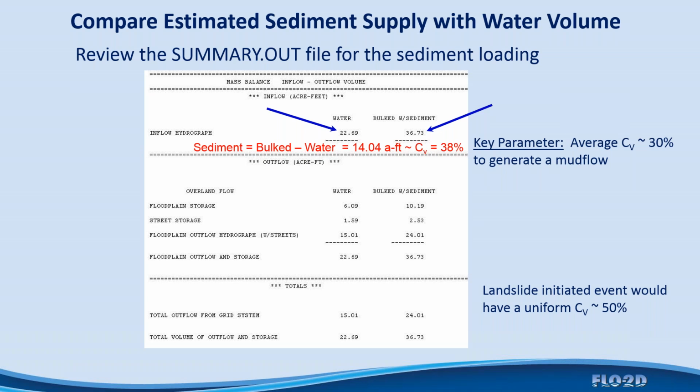Then you have this recessional limb, which is much more dilute, and it's running over. You might have 20% concentration by volume prior to the frontal wave, and 20% on the recessional limb of the hydrograph, but you may have 50% on the rising limb of the hydrograph before the peak arrives. Once the peak arrives, you're starting to dilute the concentration by volume, and you're dropping from 40, 45, maybe 50 to 55% concentration by volume as the peak mud flow concentration by volume. You're dropping that to maybe 40% or something when the peak flood discharge passes by the fan apex.